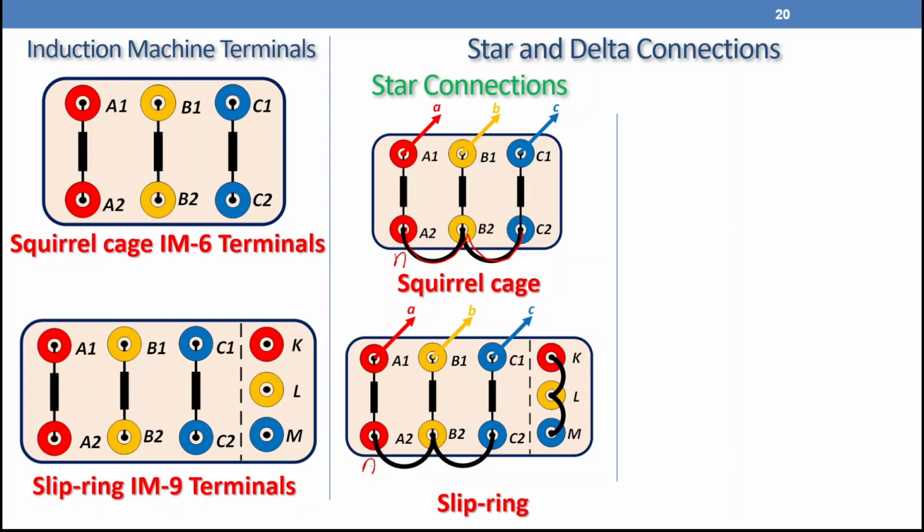Why do you want to short circuit the rotor? I'm going to explain that one in detail when we cover the theory of operation in the next video. But now, to have the motor action, we need to close the rotor. Another question, can we have the neutral point at A1, B1, C1 and feed the motor from A2, B2, C2? Yes, no problem at all.